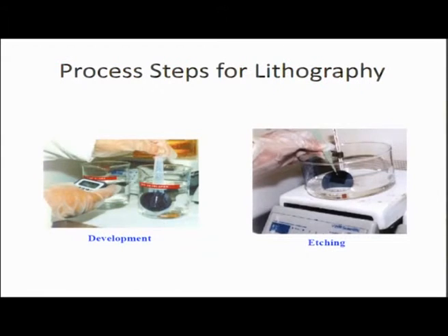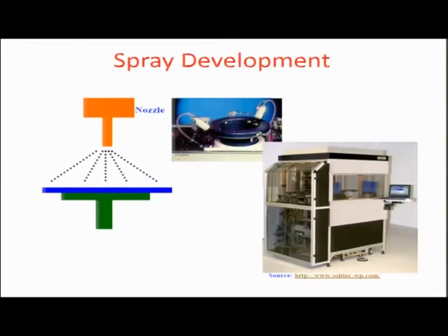And then you have, after the lithography has happened, a timed development where a solution is used. A wafer which is already exposed to light is dipped in, and material is taken off, so that you have the sacrificial resist patterned on the wafer, and you use again an etching solution to etch off the film underneath the resist, so that you could make vias or crevices or craters into that particular film which you are etching through this process, for which the resist is actually an etch stop. So, this is how different steps of lithography are executed.